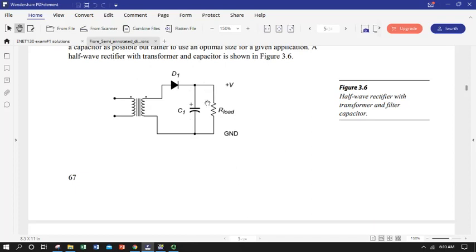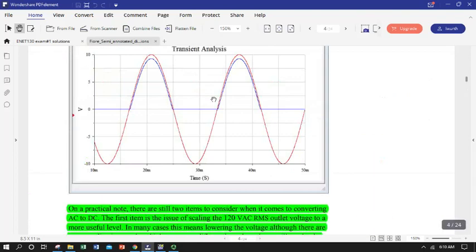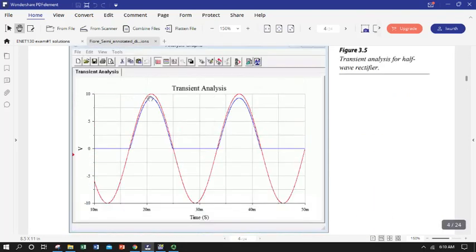So it'd be kind of nice if we could time this thing so its tau was somewhere on the order of the time between these peaks. So we want tau to be something close to this peak to peak time, which is, oh, how convenient, the period of the input waveform. I know the frequency, I just invert it, I get the period.